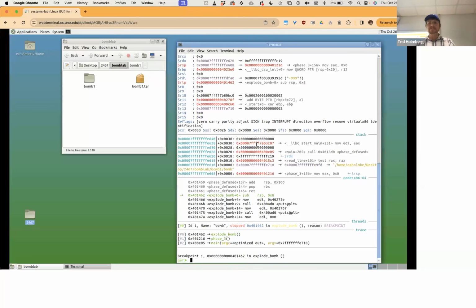I have to look at the function call, but I wonder now if it was changing my signed value into an unsigned value, which would then mean that I was above 7. It was above and not green. You're right. It was. So that means it was for unsigned data, which means the negative value was not treated as a signed integer, it was treated as an unsigned integer. And so my most significant bit is going to be a really big number.